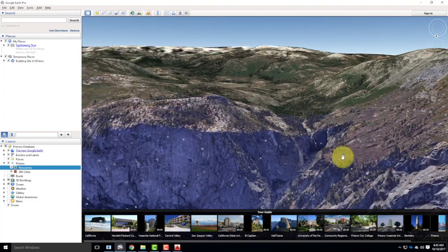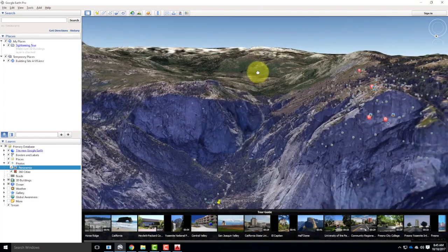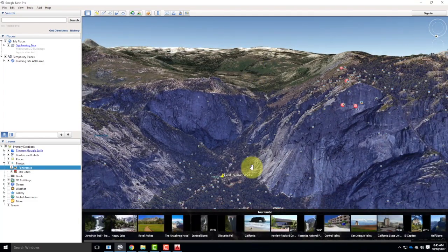There we go. I got stuck on Half Dome, sorry. Anyway, so play around with that, give yourself a little bit of a sense. It's important to know what north and south are so you know which direction your building's facing. The north side of your building is the side that has the view, so you want to make sure that's the side that has the windows on it. It happens to be convenient because you can get large windows without big solar heat gains without a problem.